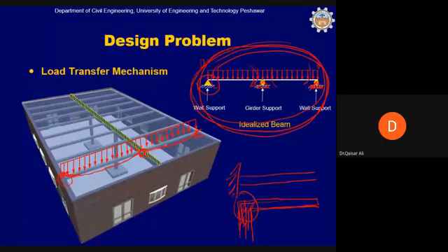There will be slight rotation also at this location where the beam is supported on girders. But if we assign a hinge support to this location, you know that the hinge support cannot move. The roller can move a little bit. It will be possible for the roller to move horizontally. So practically there will be slight horizontal movement at this support, at the intermediate support.